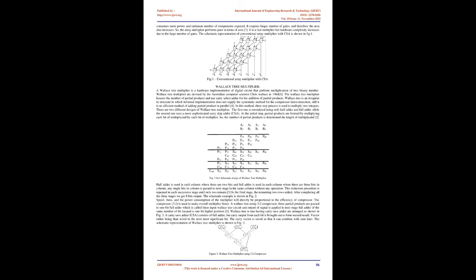The partial product is generated by multiplying the multiplicand with each bit of the multiplier. The partial products obtained are then shifted depending on their bit order and are finally added at the last stage. The number of partial products that are generated is equal to the number of multiplier bits. Array multiplier has a very regular and systematic structure. Its delay becomes very large for a large word length.